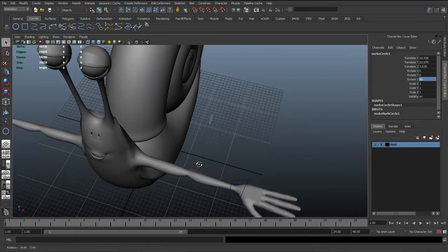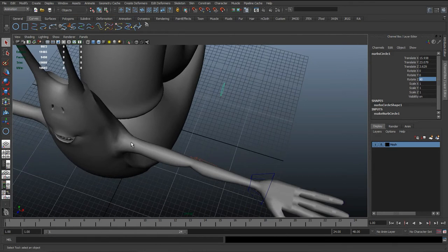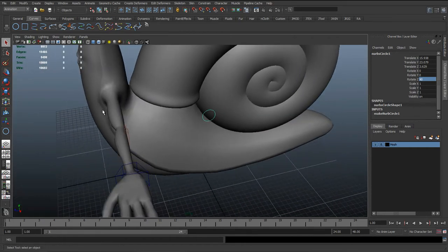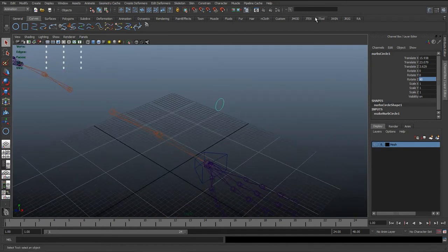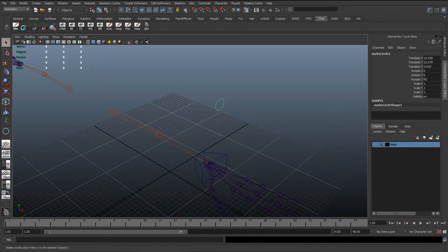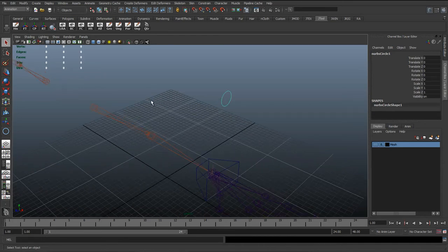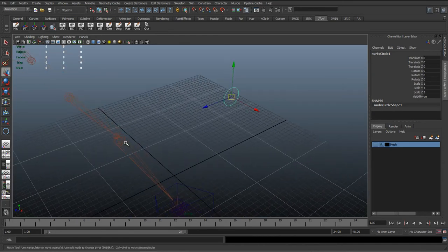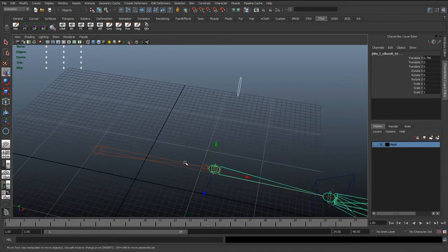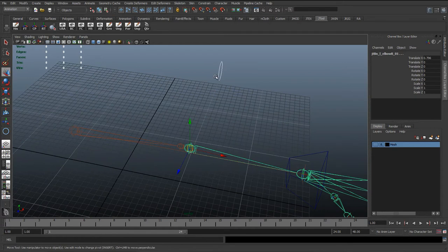into place. So as we were saying earlier with the RP, the rotate plane IK, this is going to be the third point, so you can start to see this sort of visual triangle. So going from the shoulder to the wrist to the pole vector and back is going to form that triangle, what we're going to use. So I'll delete the history, freeze transformations on that again. So what I'm actually going to do here is select both the curve and the joint that we snapped it from. So we snapped it to this joint here, the elbow joint, and moved it back.